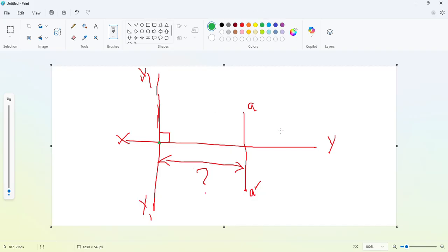Now again we are considering the same right view, which will be on LPP. So from this point of intersection, you have to draw an inclined line at 45 degrees with the XY, and the direction of that line will depend on the direction of the top view. The top view is above the XY line, so you have to create a line at 45 degrees with the XY line in the direction of the top view.